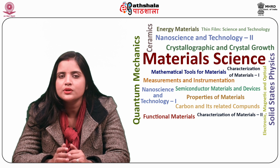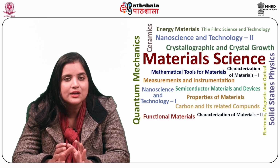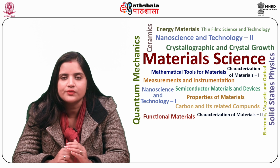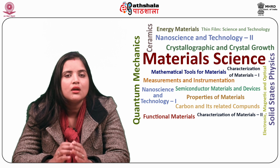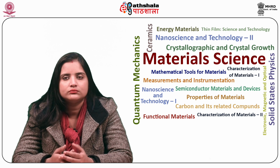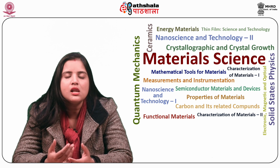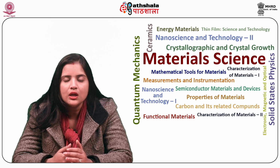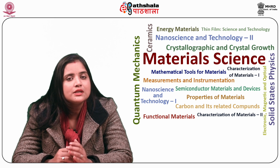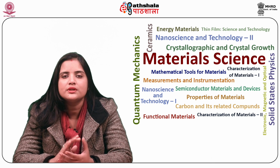It is also used in the semiconductor industry to deposit gold, ceramics, etc. onto a variety of substrates, for example plastic, ceramic, silicon, gallium arsenide, etc. Pre-treatment of the substrate involves mechanical and chemical cleaning, and vapor honing for improving film adhesion. Additionally, the reaction chamber must be clean, leakage proof, as well as free from dust and moisture.